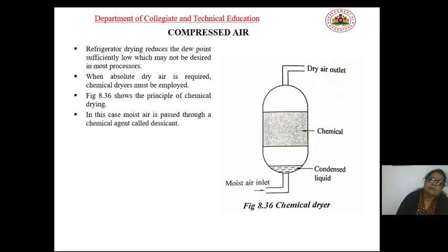Refrigerator drying reduces the dew point sufficiently low, which may not be desired in most processes. When absolutely dry air is required, then we can go for chemical dryers.